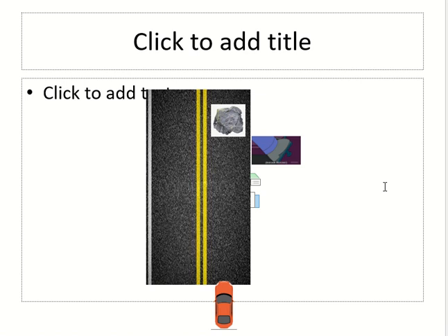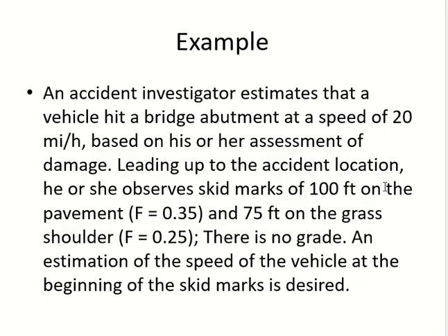Let's say there was a rock on the road, it fell from the moon, and you saw it, and then you push the brake. What do we call the time between looking at the rock and pressing the brake? The perception reaction time. That is before the braking, and then we have the braking distance.